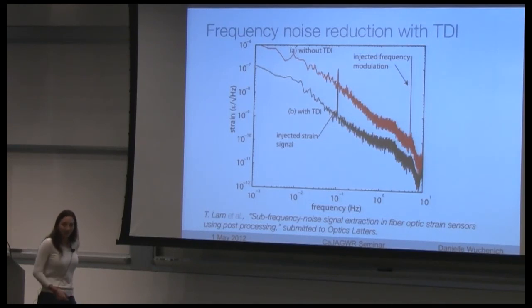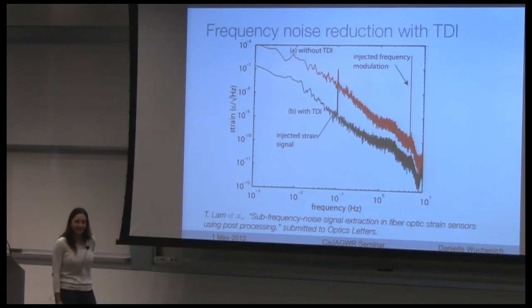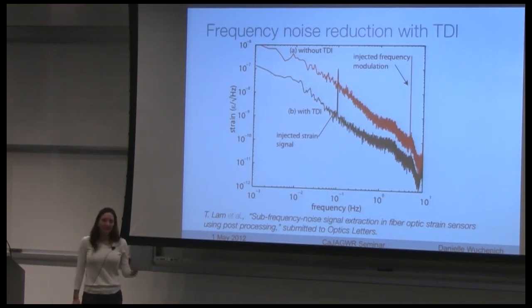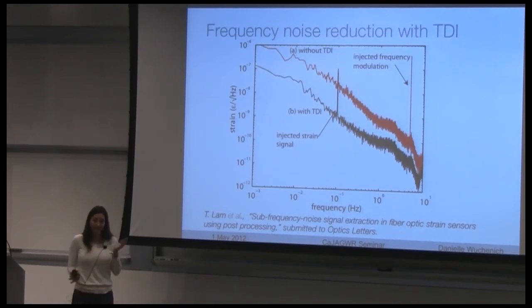But at low frequencies you always have an issue. In all heterodyne measurements you hardly reach the shot noise. You're usually limited by other technical noises in heterodyne readouts at low frequencies first, be it laser frequency noise, be it environmental, or other 1-over-f noise like thermal things.